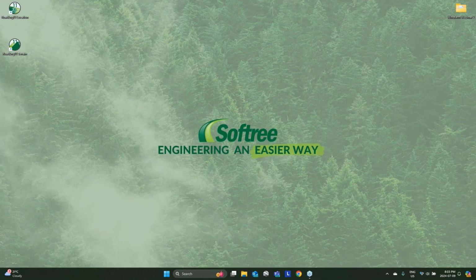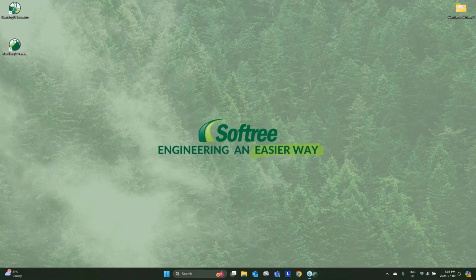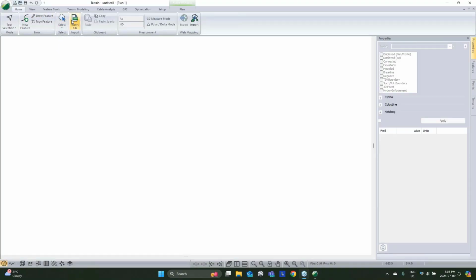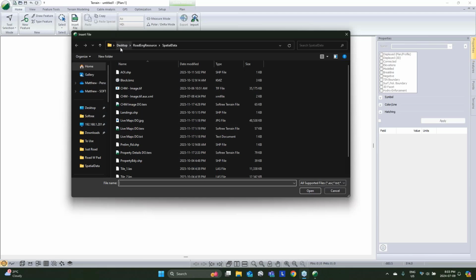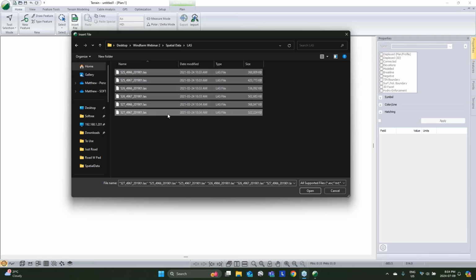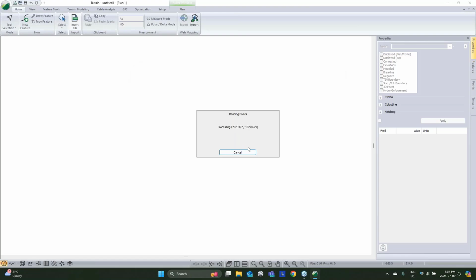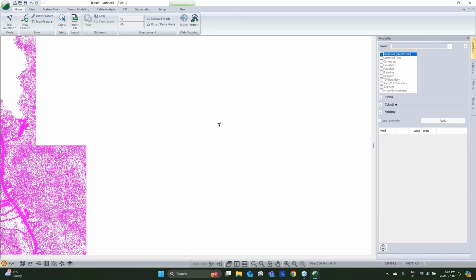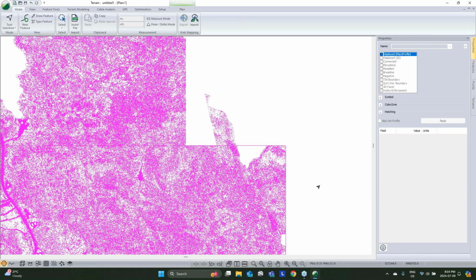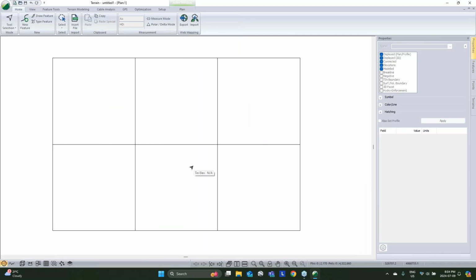We're going to start out right from square one, in Terrain. We're going to end in Location for our proper linear infrastructure design, but we start in Terrain to bring in our survey data. In this case, we're going to use some LAS data, and we support a bunch of different file types: LAS, LAZ, DEM for the common LiDAR formats, but also conventional survey data and other formats from other software. So I brought that LiDAR data in.